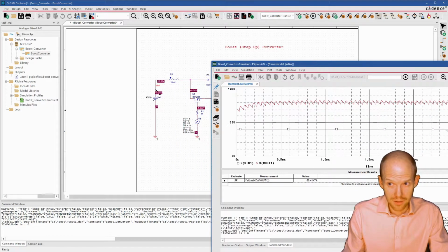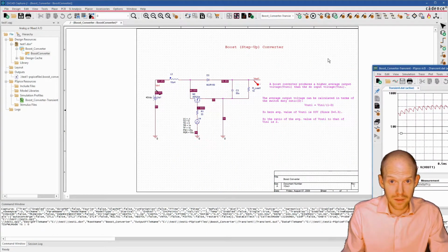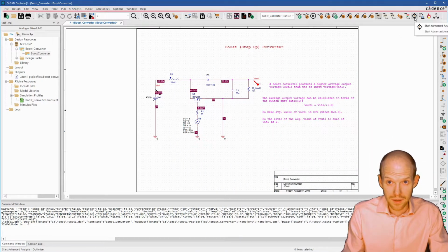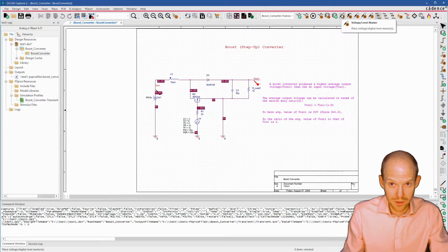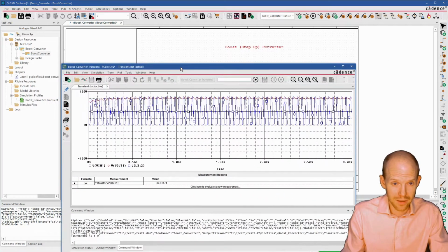But you can also use these probes up here. So if you click on, this is the regular voltage probe, this is the differential probe, and this is the current. So if we want to get the voltage here, we can click on that, and you'll see that was added in as this one, and it's called L3. That's pin 2, I guess.